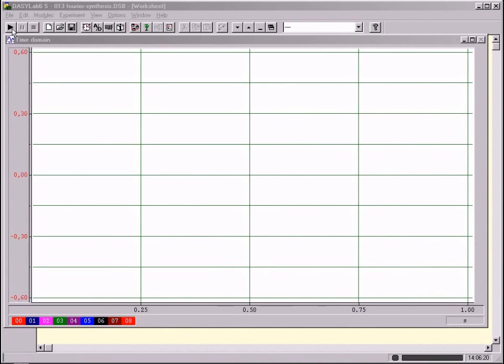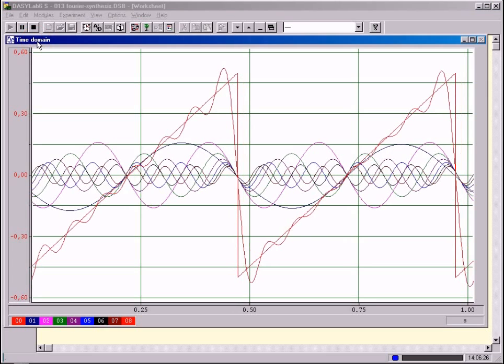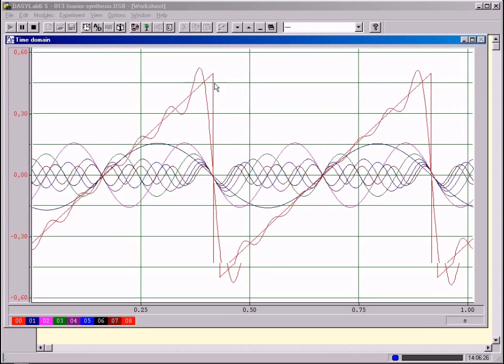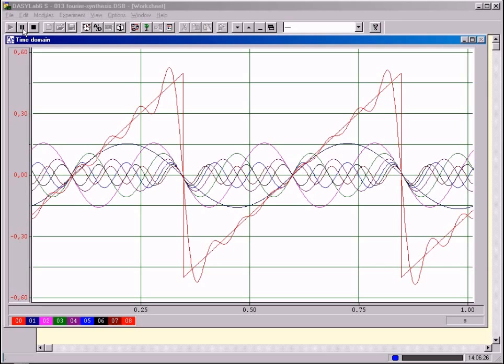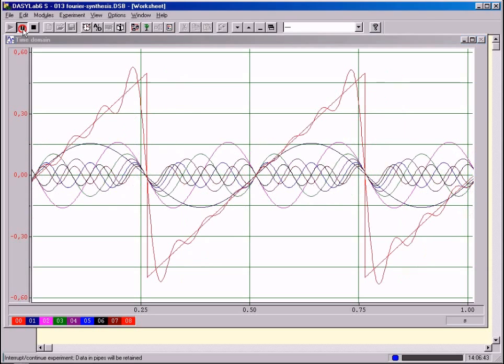This is a second illustration of the Fourier synthesis. Using the example of a periodic sawtooth signal, it is shown that sawtooth-like signals arise by adding appropriate sinusoidal signals. Here are the first 6 of the theoretically infinite number of sinusoidal signals which are required to obtain a perfect linear sawtooth signal. The following can be clearly seen. In some places, 4 are visible here. All the sinusoidal functions have the value 0. At those points, the sawtooth or the sum has the value 0.